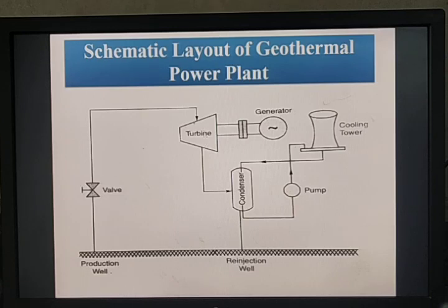There are four types of geothermal sources: hydrothermal system, geopressured system, petrothermal system, and magma sources. But the one preferred in a geothermal plant is magma resources. The land chosen for generating power in a geothermal power plant is dry rock land with high temperature. In the geothermal power plant, the temperature is maintained from a minimum of 150 degrees centigrade to 300 degrees centigrade.